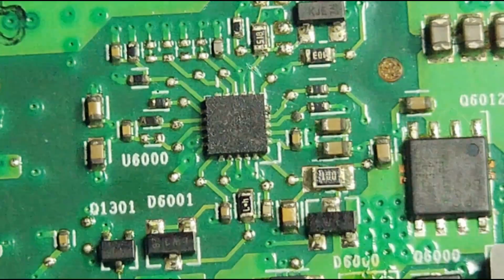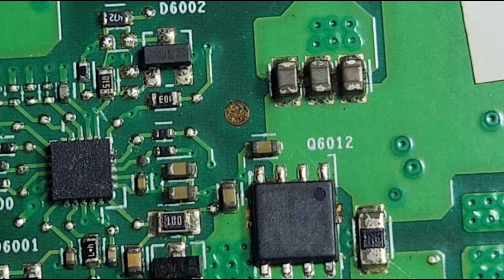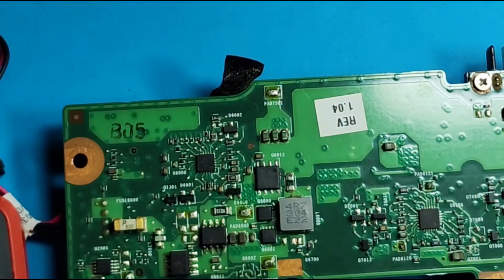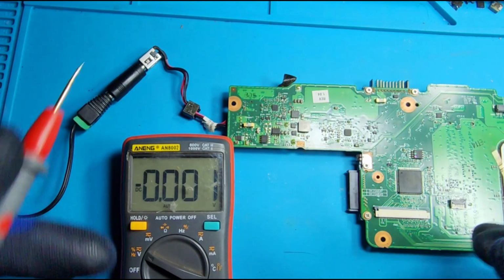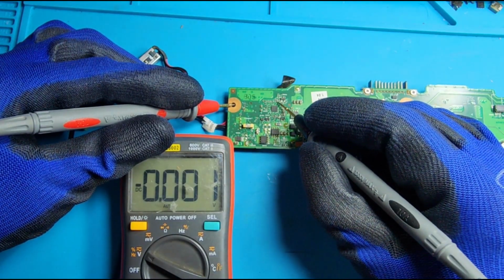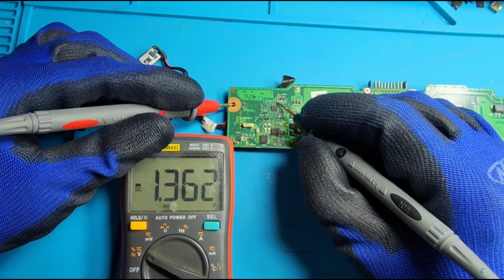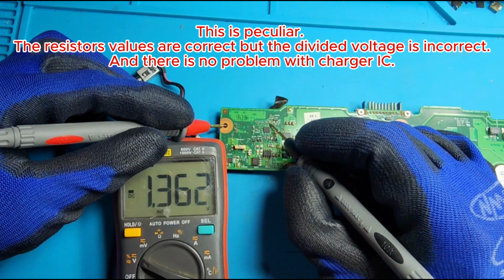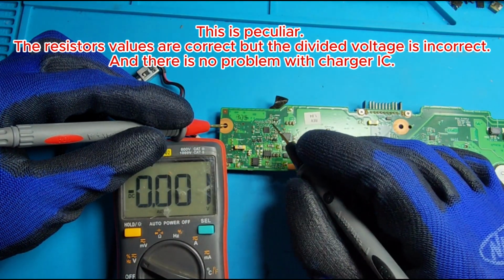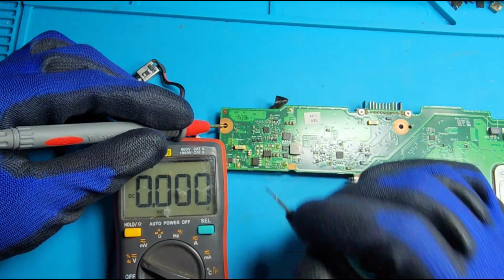Okay, now let me connect the adapter and check the voltage on the resistor divider. You can see the resistor values are appropriate. Still we have 1.3 volt. I don't know why there is a different voltage. According to the resistor divider calculation, we should have around 2.8 volt.